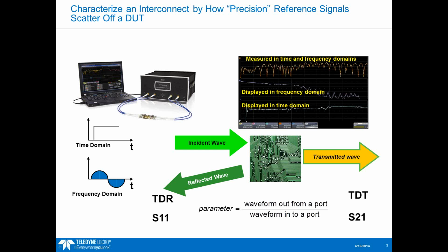Yeah, so when I just answered one of the questions, moving some cables may affect the results. If you bend a cable, for example, depending on the quality of the cable and the type of cable, the phase of it might change, and that can affect the results. It just depends on what you're using. So it's not necessarily the impedance that's changing. It might be the phase delay.